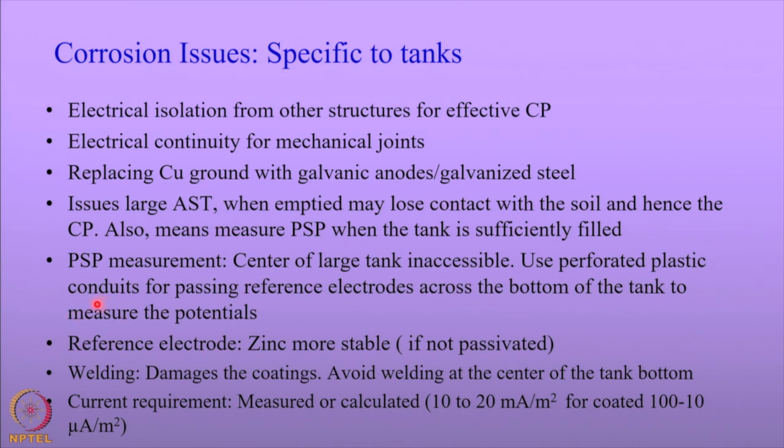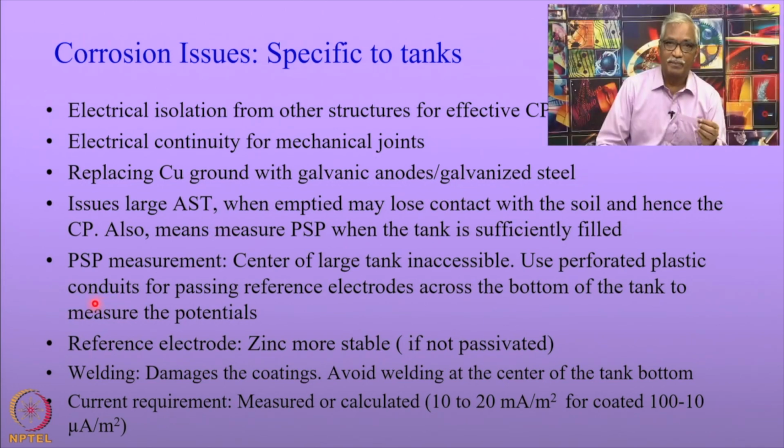There is one more issue that is problematic for tanks, that is how to measure the structure to soil potentials, especially in the inaccessible areas. You would notice that there are tanks of very large diameter, of a few meters, in which case the reference electrodes cannot be accessed at the bottom of the tanks.